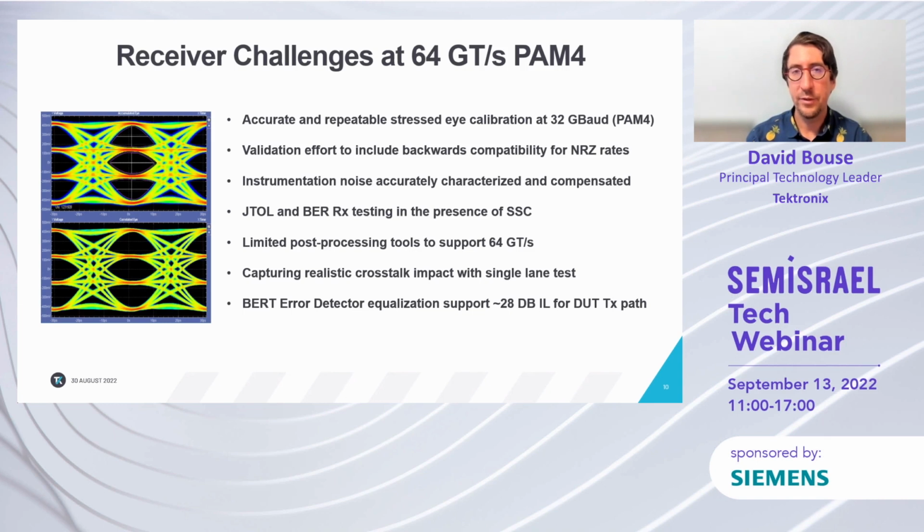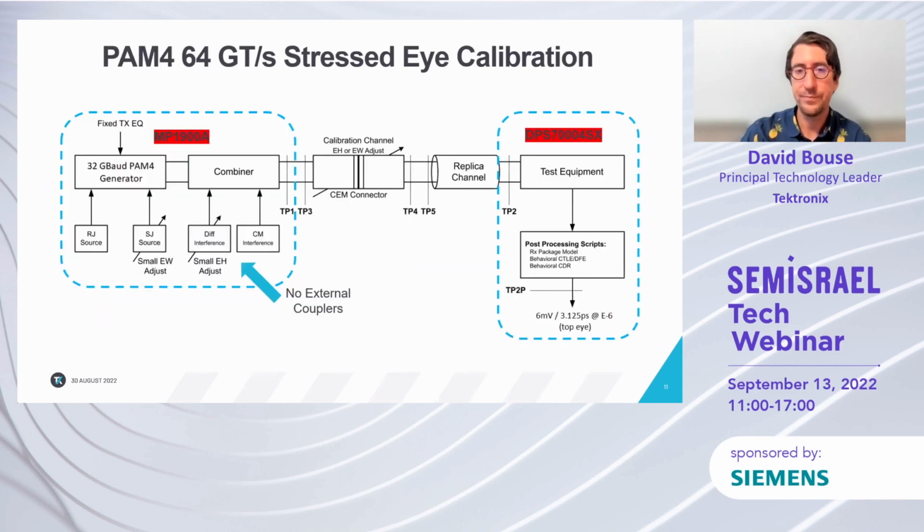And then, also for receiver testing, we have to get that transmitted data back to the bit error rate tester, or the BERT, so we can do that comparison, and ensuring we're not introducing bit errors in that return path or that back channel is critical.